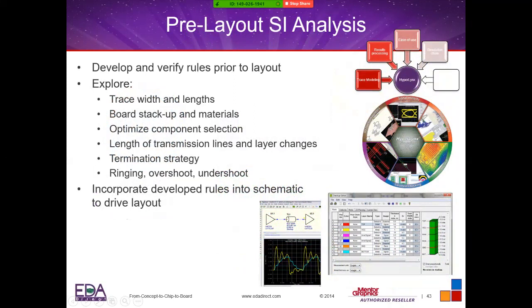You have an oscilloscope that you'll be able to use. There'll be a layer stackup that you can look at to find out how your layers are used, what metals you're using, and impedance controlled information. So for those of you that want to do this before you start laying the design out, checking out your schematics, you've got full SI analysis.